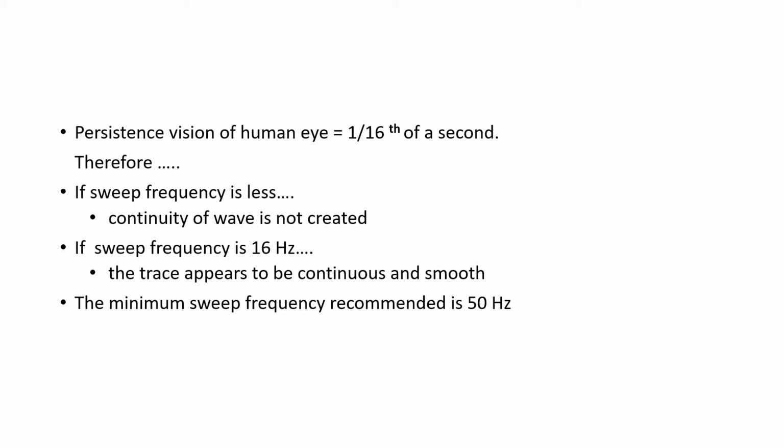The conditions are: use a low frequency sweep generator, use the CRO in automatic or external triggering mode, and connect the signal to the vertical input and the external trigger to the external triggering input. The minimum sweep frequency recommended is 50 Hz.